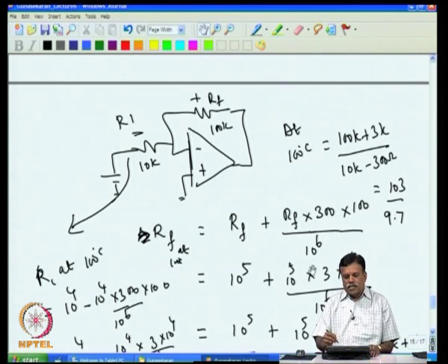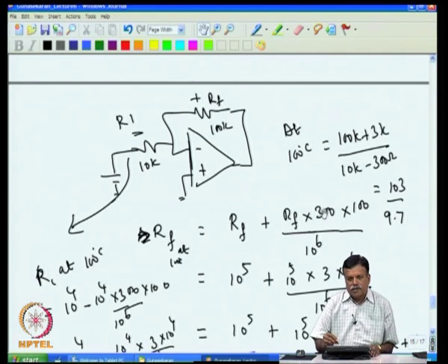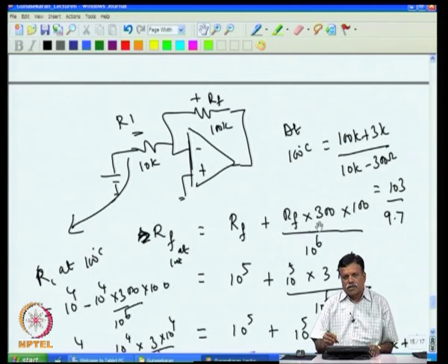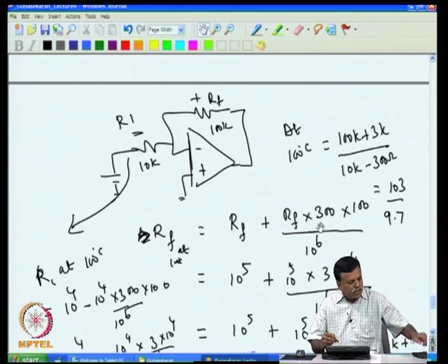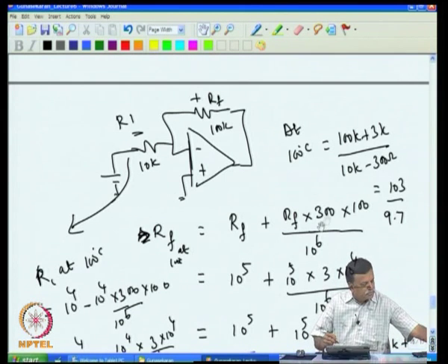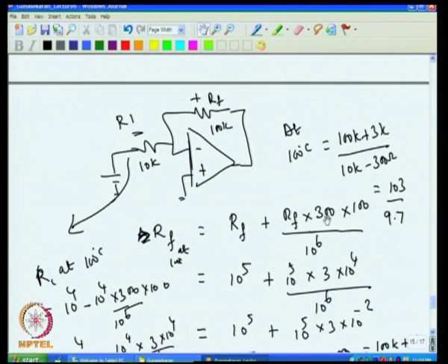So, you have resistors of various values available, right from 10 ppm to 300 ppm, and of course, cost goes up. If you are looking for low drift, then automatically the cost goes up. So, one has to make a compromise, whether you need a low drift resistor or not, that depends upon the application.